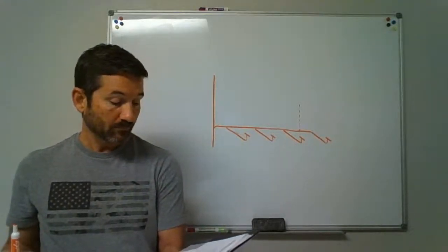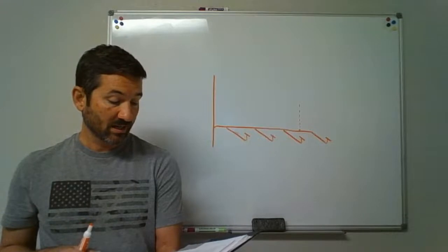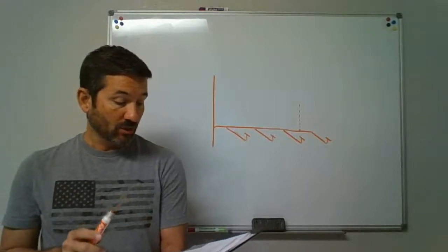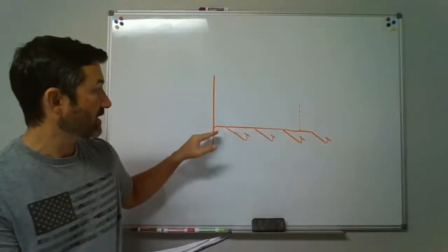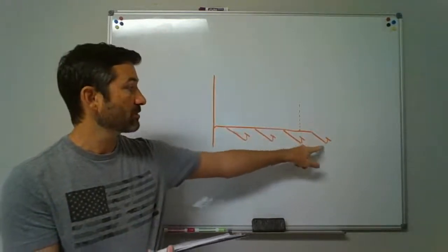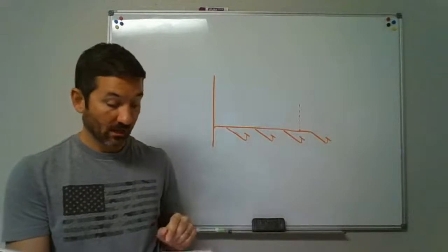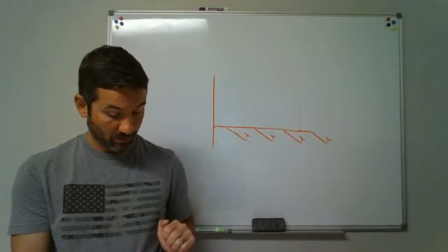Okay. The vent connection, where does it connect? The circuit vent connection should be located between the two most upstream fixtures. So this is upstream. Everything's flowing this way into the stack. So there's your two most upstream. It's between the two most upstream, as I've got shown. Okay.